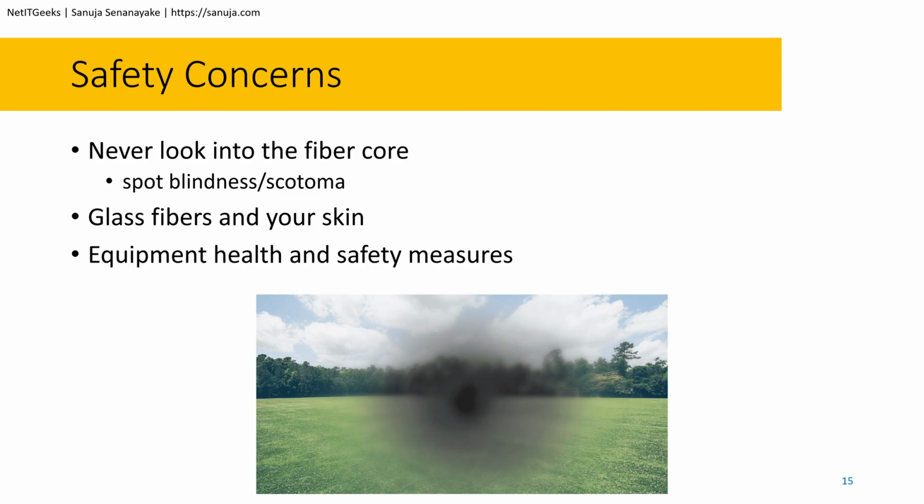hand. If you ever get those glass fibers inside your skin, you can use tweezers to try to get them out. And if you still feel there are maybe glass fibers inside under your skin, you need to seek medical attention as soon as possible, because that could create medical complications down the road if you just leave that fiber inside your skin. So you need to take all of those into account. You need to be careful when you're working with fiber optics.